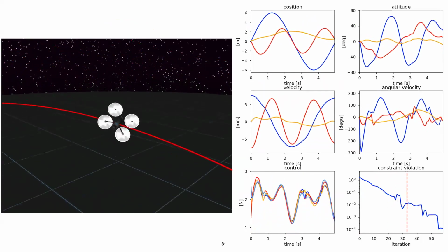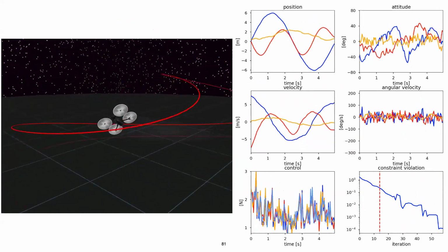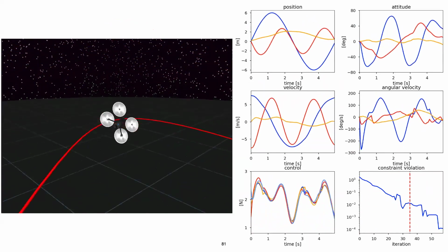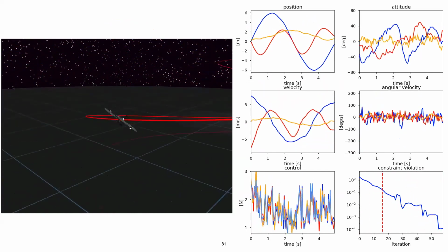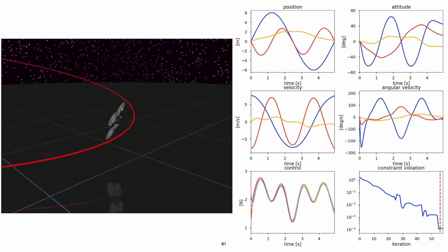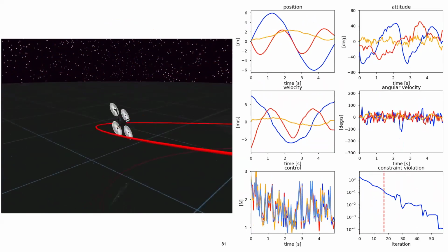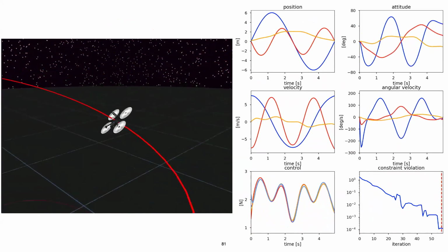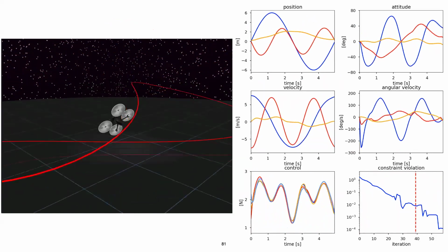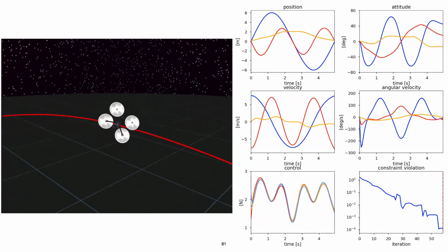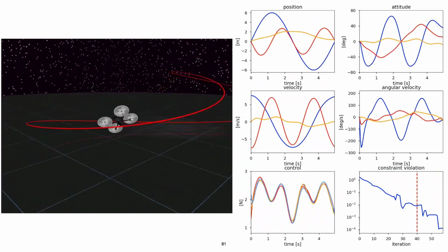We then revisit the quadrotor, which again, for MPPI with no derivatives but an insane number of samples, had trouble effectively stabilizing this quadrotor about just an initial shove. And now I'm making it track an elevated figure eight. And what we see is that the control itself looks great, looks smooth, looks very optimal. Then we see how this thing converges, and we get great constraint satisfaction. So our convergence on an optimal and feasible trajectory looks pretty good.